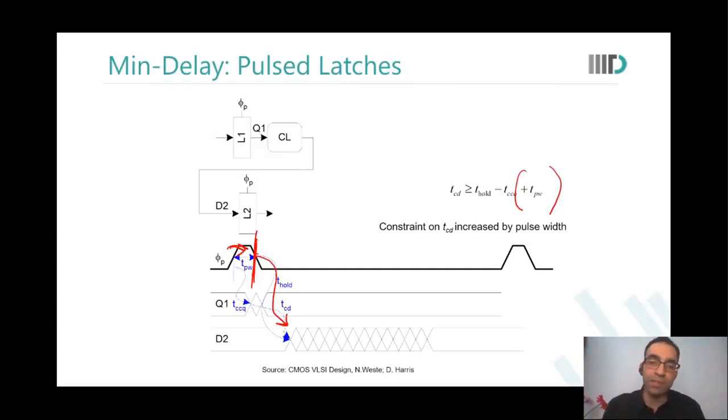The most important aspect is pulse latch is much denser than a flip flop. It has much lesser number of devices than a flip flop, so it consumes much lesser area. Lesser area means faster also, lesser leakage also. Area is gold. So if everything else is equivalent, I may still want to use pulse latch.